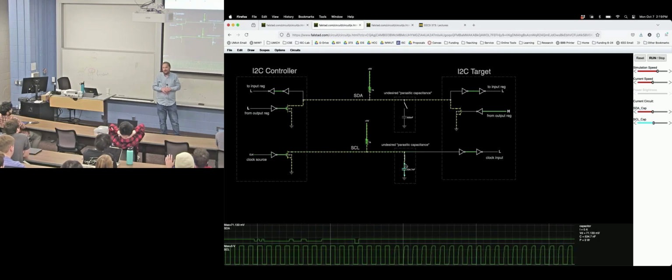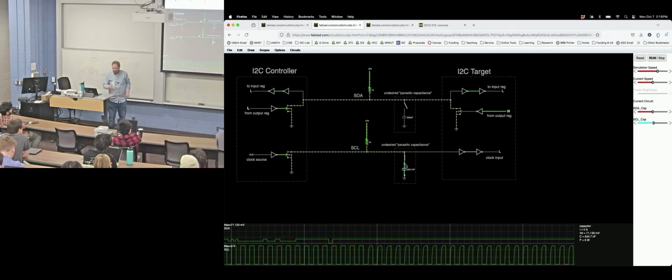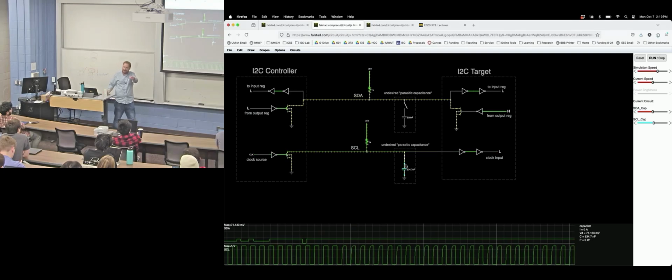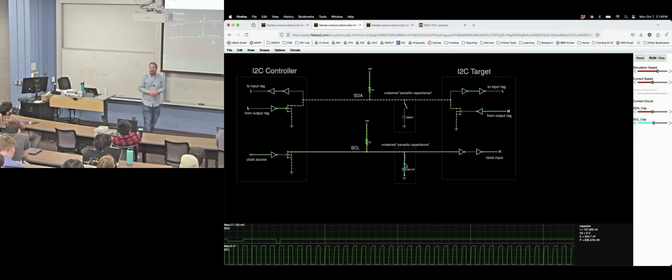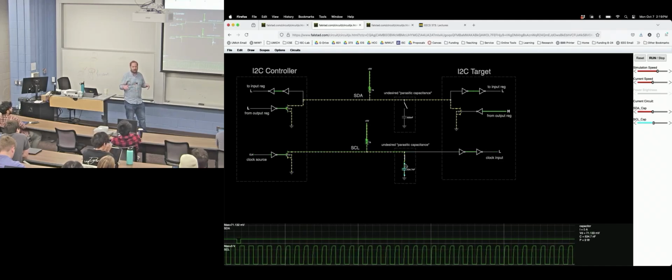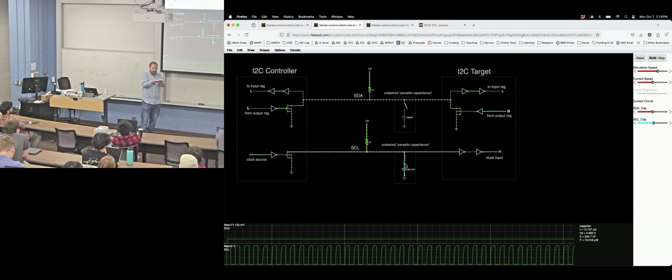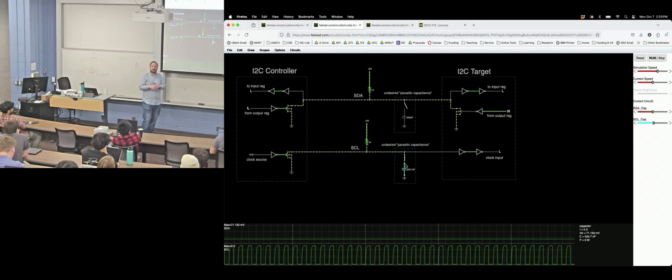So like if you have a bunch of traces and they're parallel, they might generate capacitance? Like physics, maybe? With physics, yes, fantastic, undeniable answer. Yes, that could be. You could have trace-to-trace capacitance. There's probably more typical ones. In fact, trace-to-trace coupling will cause interference where data going through this line will actually get coupled on the other line. That's probably the issue we care about more than capacitance.